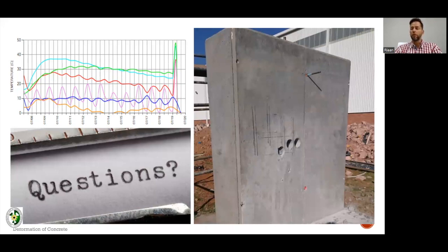Because if you don't know how much reinforcement you need to add to mitigate your temperature gradients, how much reinforcement are you putting in there? It needs to be a real amount, where you are able to say, okay, I know I'm going to hit 48, I'm not going to hit 35, I'm going to have a gradient differential of 40 degrees or 30 degrees or maybe just 20. I can design for that.